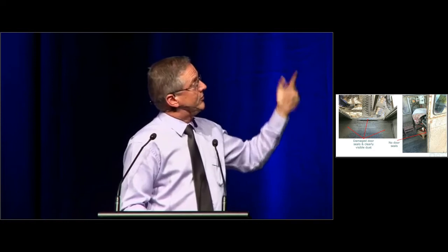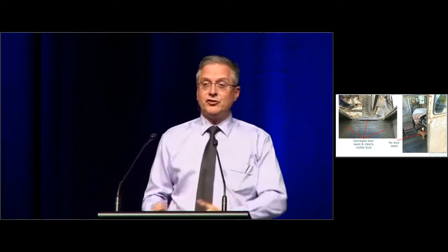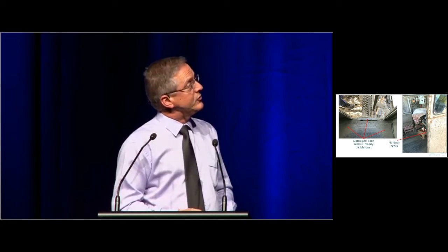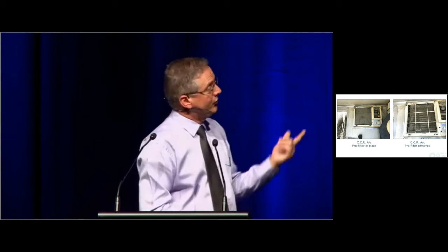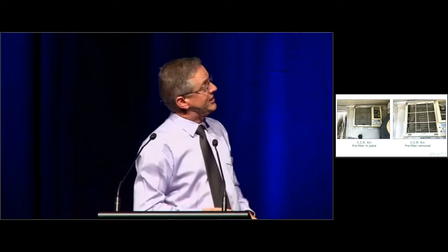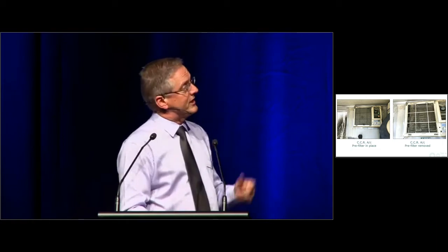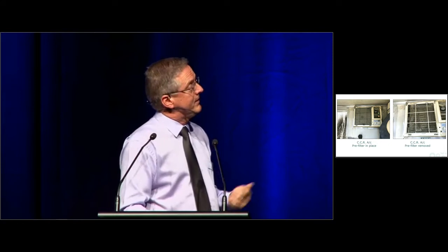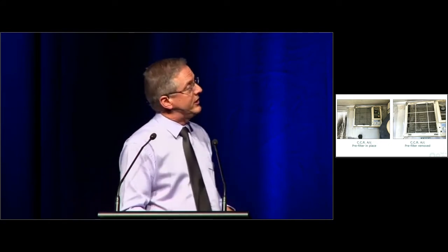Damaged door seals, piles of dust clearly visible inside the control booth. And then, again, door seals on that control booth there. And often these little control booths are positioned right above the primary or above the jaw crusher so that they can see whether there's a blockage. So you'll have a little cabin with a busted door and this sort of air conditioning system right next to their primary dust source. And it's not surprising that some of the results I'm finding from static sampling are showing a particular problem with ingress of dust.